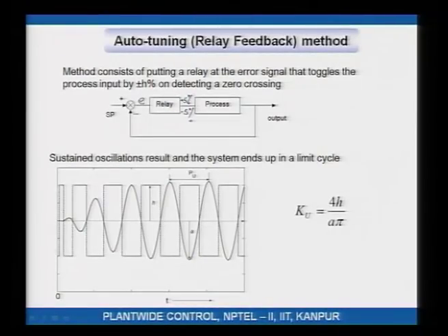If you put in a relay in a feedback loop system, this is what happens, and that is shown in the figure. What happens is, the output toggles, the error crosses 0, and as the error crosses 0, the state of the relay goes from here to here. In response to that, the error crosses 0 again, toggles down, starts to go up, because the output has toggled down, it starts to go back down, crosses 0 again.